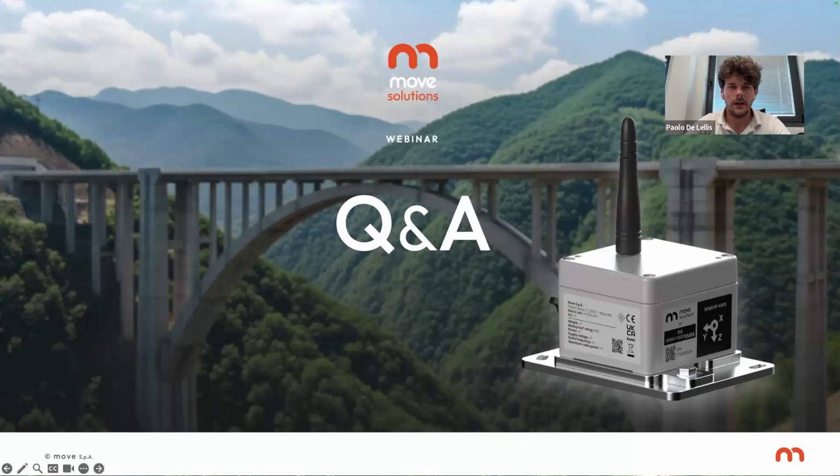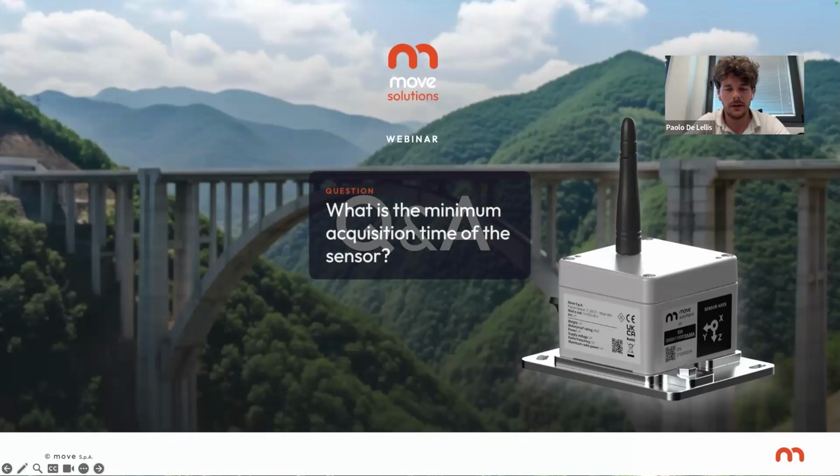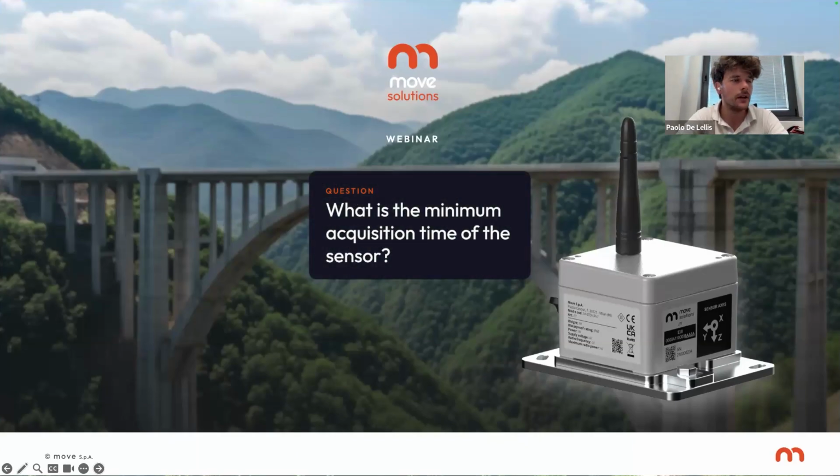So another question is regarding the minimum acquisition time of the sensor. With this question, we answer also with the data that you can obtain with the tool. With the new version of the tiltmeter, V4, that you can find on the market today, you can record an event every 30 seconds. So every 30 seconds, you have the possibility to record the angle from the sensor, the two angles.